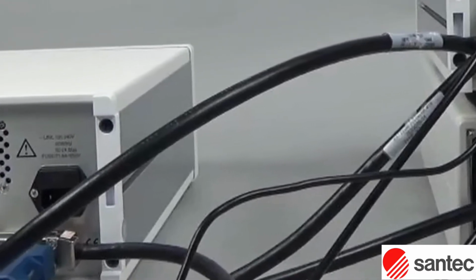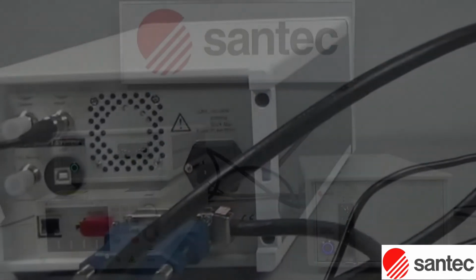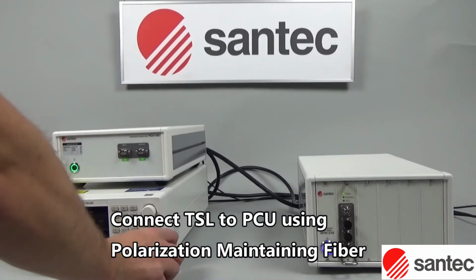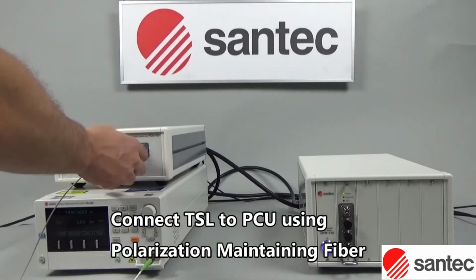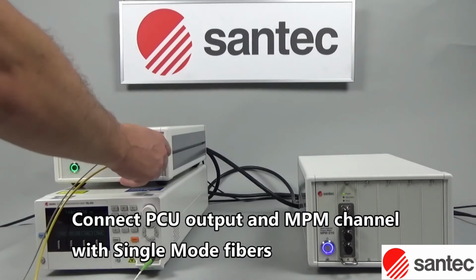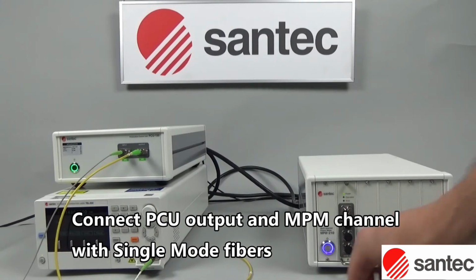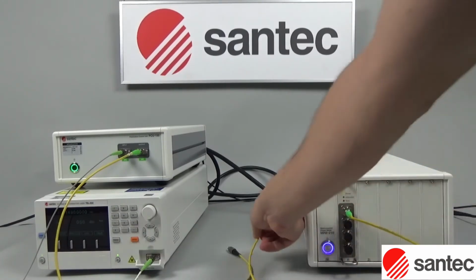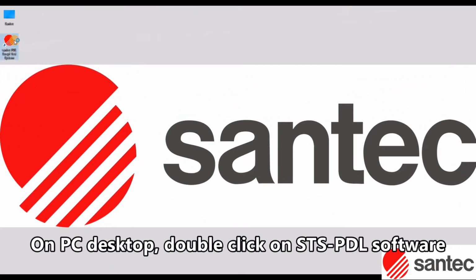Now that all electrical connections are set, let's go back to the front panel and check what kind of patch cords you will need. First, connect the TSL to the PCU via polarization maintaining fiber. Then, connect the PCU output and the MPM channel with a single mode fiber. Now that all the hardware is set, we are going to use the STS-PDL software to control our instruments and measure our devices. Just go on the PC desktop and double-click on the link.